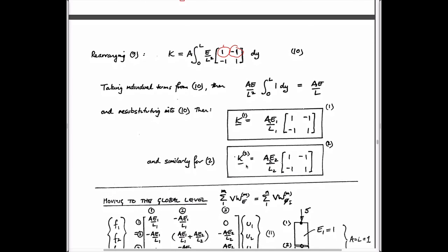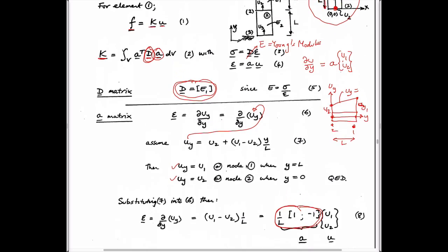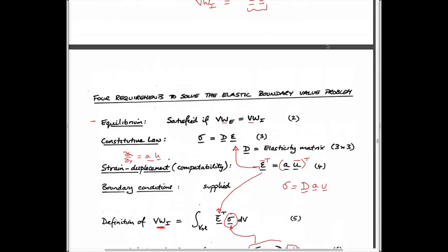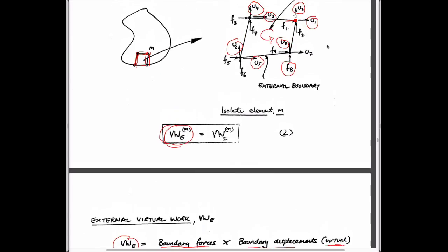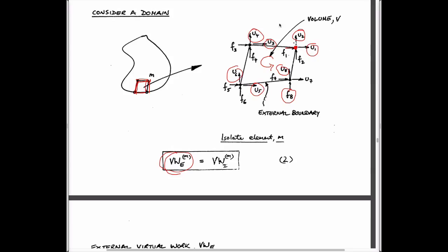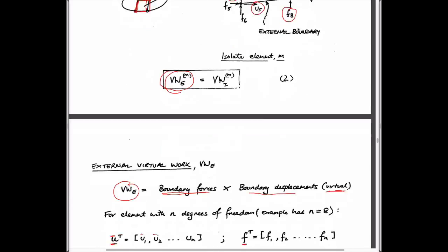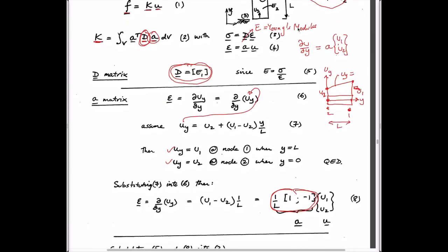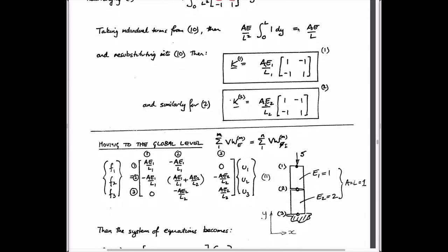We should caution ourselves that in this particular case, we have 1 degree of freedom, so it's still a one-dimensional problem. The same as the number of nodes, we have 1 parameter per node. That won't always be the case, and it sometimes gets a bit more complicated, for instance, when we have 2 degrees of freedom per node. But for this particular case, it ends up being identical to the equation we had before.